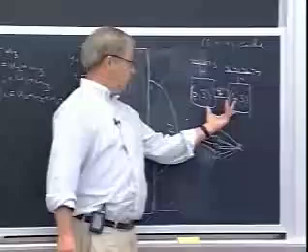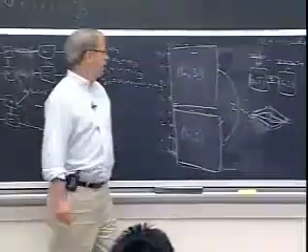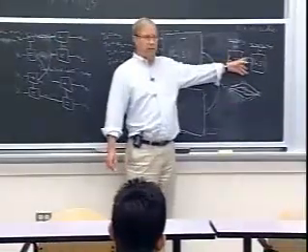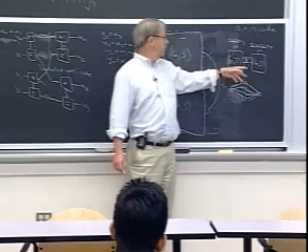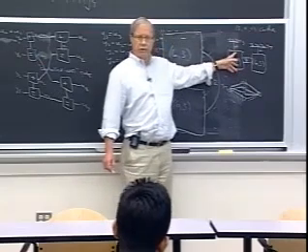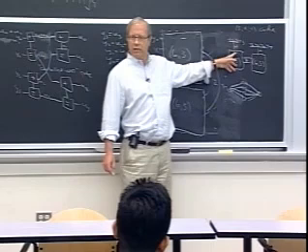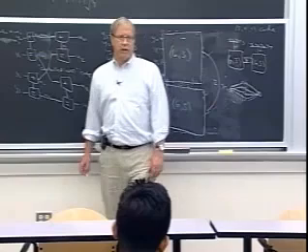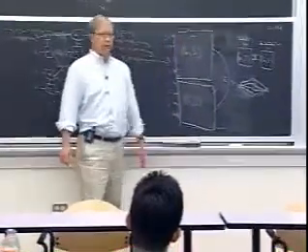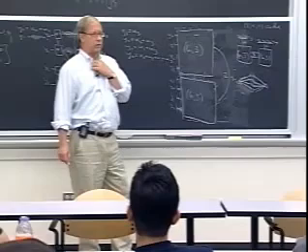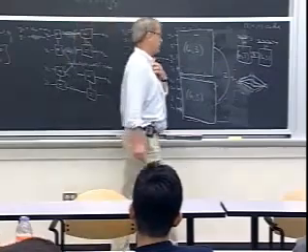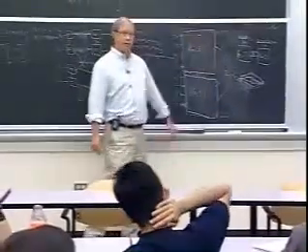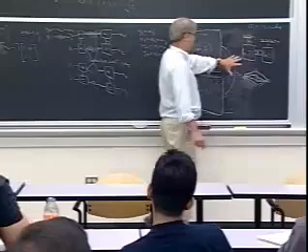Okay, so this is indeed cycle-free. What's the difference between this realization and the other one? Well, first of all, we've got 4 states in this cycle-free realization, and we've got certainly much larger constraint code here, which will turn into computational complexity when we go to decoding. Now we've got a branch complexity of 8, whereas we never had anything larger than 4 in the zero-sum constraints of the previous diagram. So in that sense, this is more complicated. Its state complexity, its branch complexity is higher than the one with cycles, but it's cycle-free.